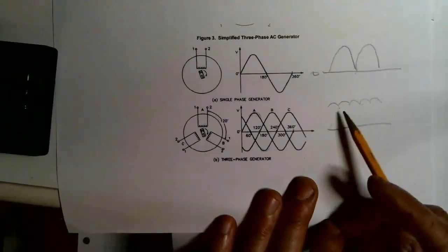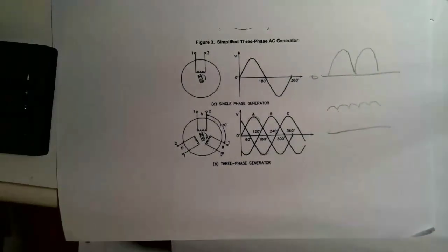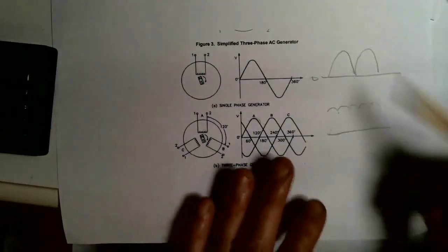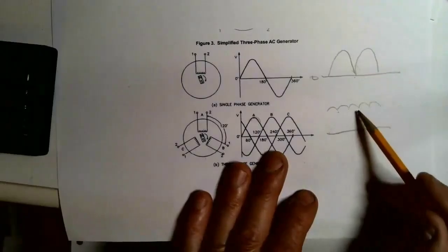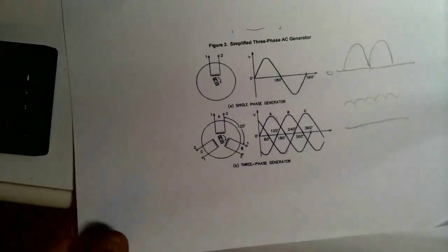And by the way, you can put a load on this, and that doesn't make the ripple worse, like it does if you try to use a capacitor input filter, like we learned, with a full wave bridge. The more load you put on it, the worse the ripple is. That's not true for this. So that hopefully explains why they use the 3-phase full wave rectifier in an alternator.